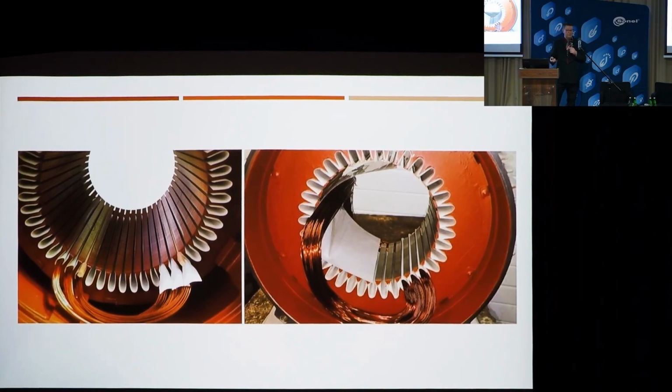An interesting situation. What do you think would have happened after the motor was assembled and started up? Do you give it any chance of lasting for long? I don't think so. That 430 megaohms we had was the resistance of those little wires lying there in that slot. Because winding wire is enamel coated, so there was some insulation there, but that enamel would most likely have chipped off due to heat and vibration. A short circuit would have occurred, and that would have been the end of it.